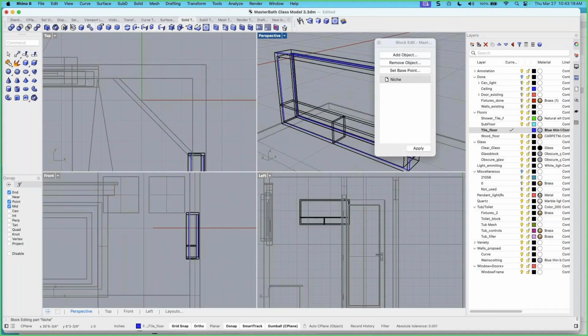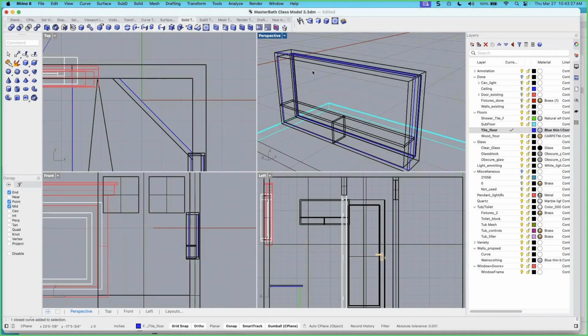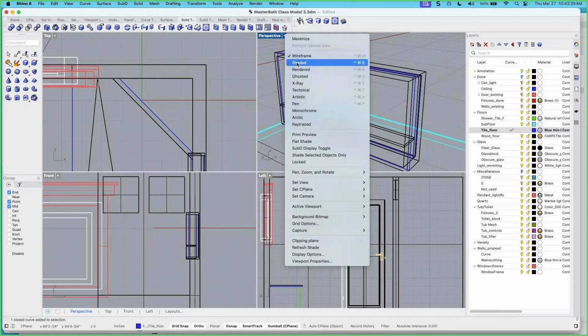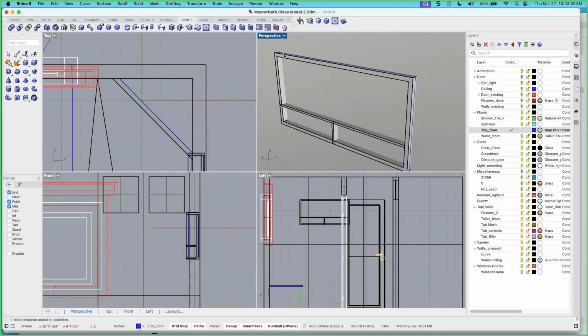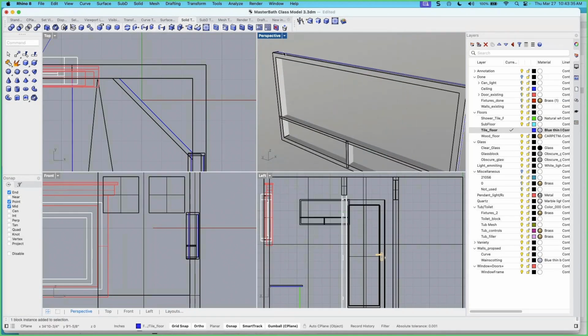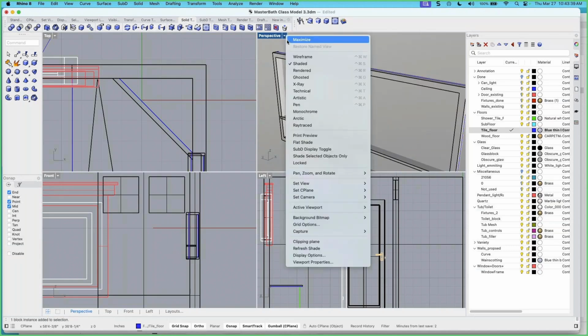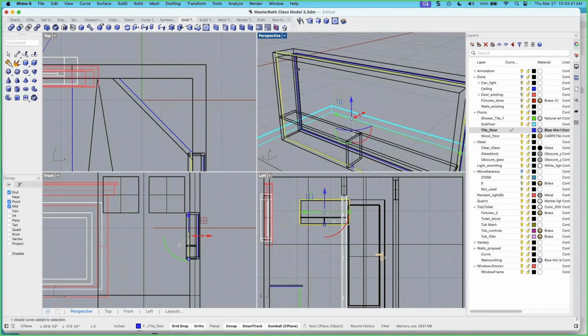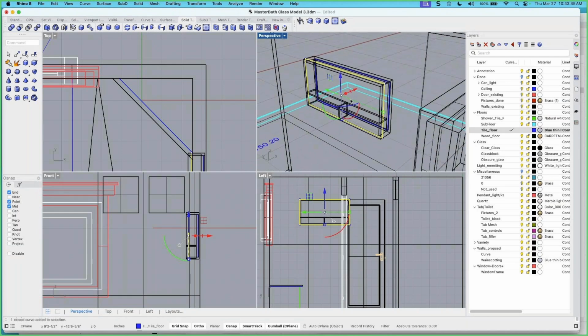So let's see, curve, remove object. It said it, oh, I didn't apply. My fault. Apply. Okay, now we should be in good shape. Shaded, and we want to pick on the curve. And it's getting, again, a little confused with all the surfaces. If you go back to wireframe, you'll be able to grab it. Okay, and now that you have the curve,